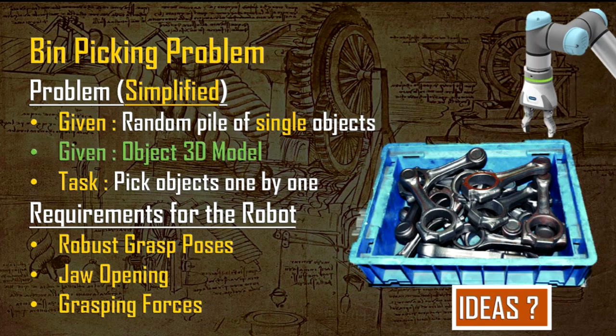And we know the size, the diameter of the circle from a distance, let's say half a meter. We know the diameter of the circle in the taken picture, and with the comparison, we can calculate the distance between the camera and the circle. That gives us the distance from the robot to the part. I don't know if I explained it well.